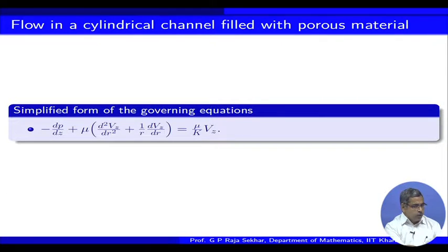Okay. So, now we have to solve this equation. Okay. So, without this term we have already obtained the solution. Now you have an additional term, so that will change the structure of the solution. Like in the previous case, earlier we were getting only polynomials, but in the Brinkman case for channel flow we got hyperbolic functions. Similarly, for pipe flow without this term we would have got a solution in polynomials in terms of r, but here we expect something else because of this.